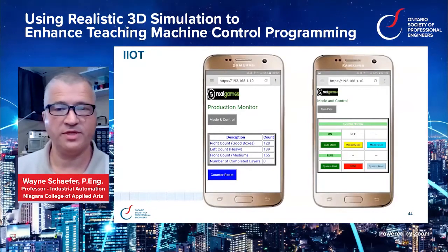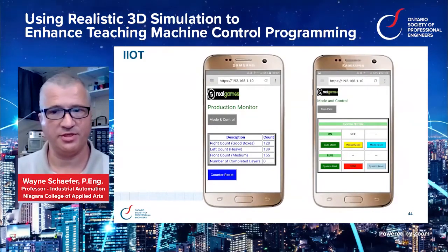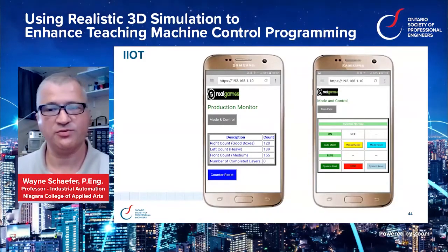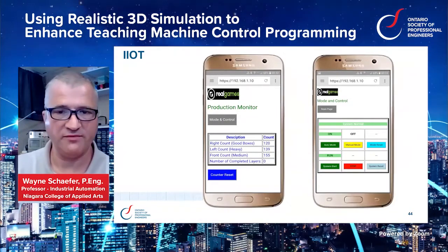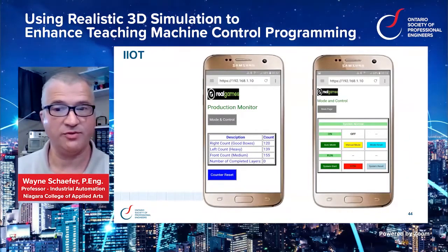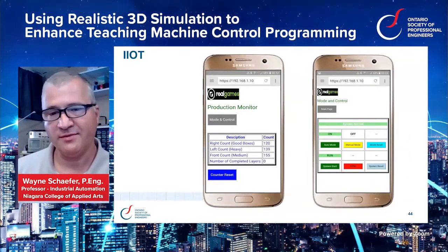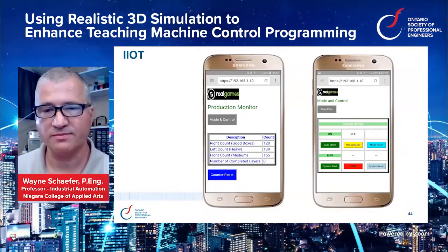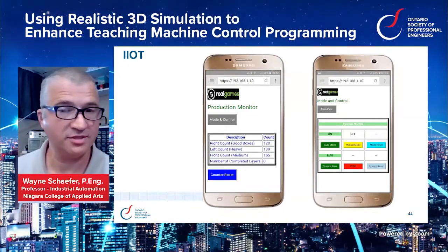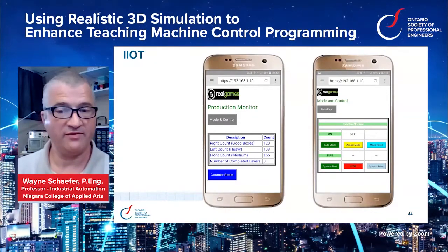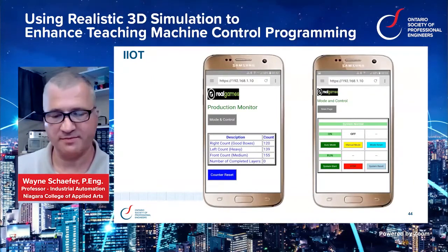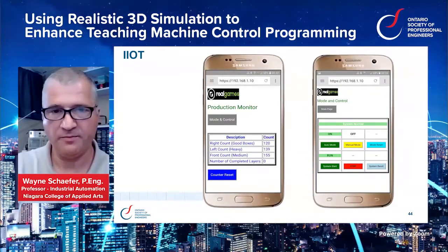Now, one cool thing about the S7-1200 PLC is it has a built-in web server. With some very basic HTML code, I can create basic screens with some usefulness. The left screen on my phone shows the box count, the number of completed layers, as well as providing the counter reset function. The right screen is the mode and system start control screen with simple status or basic alarm messages displayed as a banner. And we have available automatic, manual, reset, run, stop, and system reset, just like we had on the main panel.